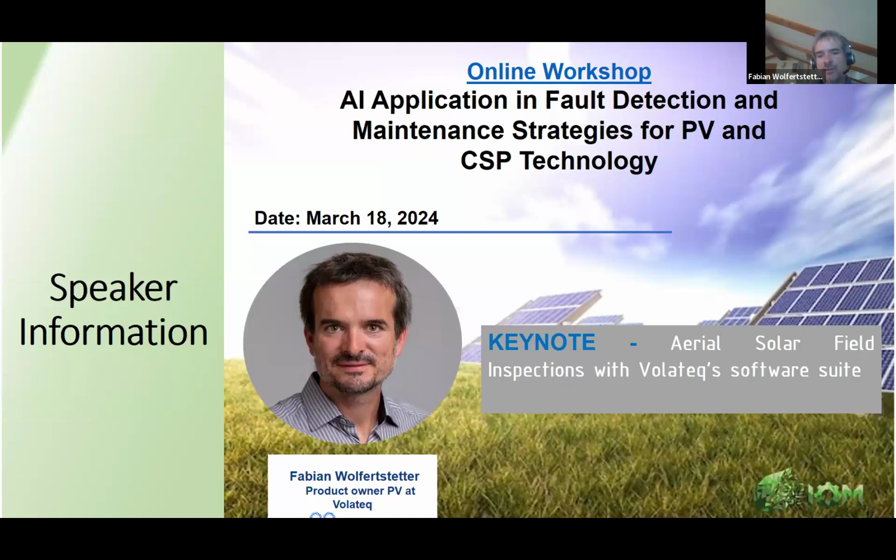It's very established already in PV technology, so that's what everybody does. Of course, if it's about insurance issues or something, you need more advanced technologies than just thermography. Let's say you would need electroluminescence, but that's very advanced and much more costly. So to get an overview of the state of your field, then thermography, the drone inspection is sufficient, yeah.